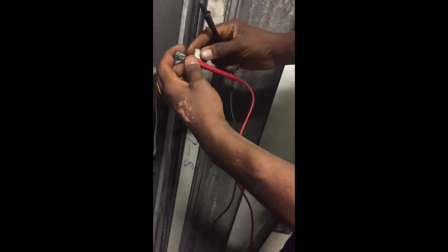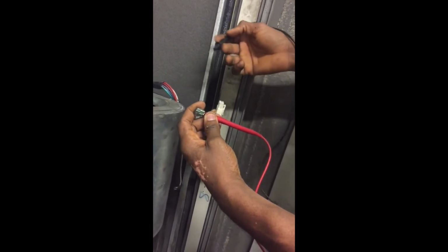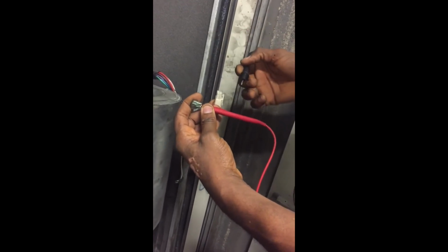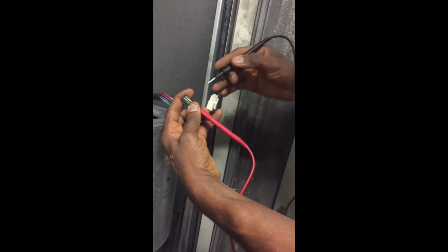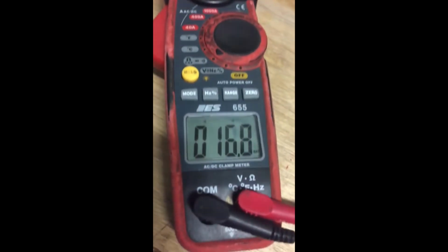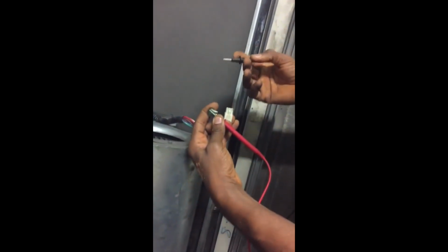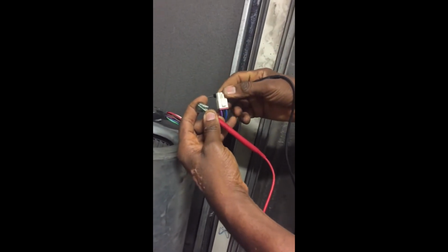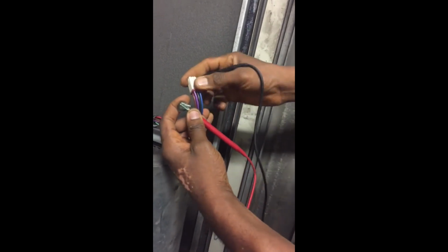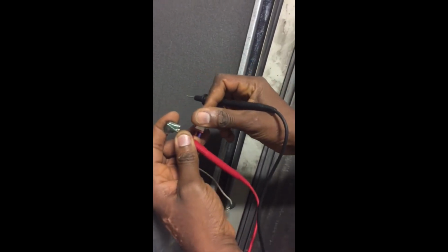In this particular case, we can use any of the speed cables as a supply cable, because that's the part through which the voltage is available before it gets to the run terminal. So let's go and look at black, which is our high-speed terminal. What is it giving us? You can see there's continuity, and then we check the other one again, which is the medium speed. Our medium speed in this case is purple, as you can see. And then between the lowest speed, which is orange here, and the run terminal, there should also be continuity.